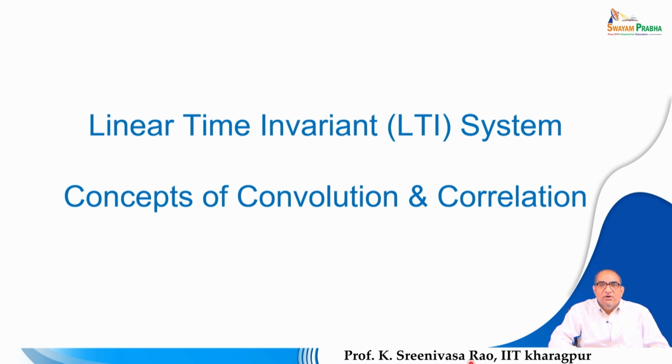We also introduced the concept of unit sample and its representation. We defined what is meant by unit sample and its use in representing a discrete time signal. Any discrete time signal can be represented as a linear combination of scaled and shifted unit samples. We started from the definition of unit sample and derived the expression for any discrete time signal in the form of a linear combination of scaled and shifted unit samples.